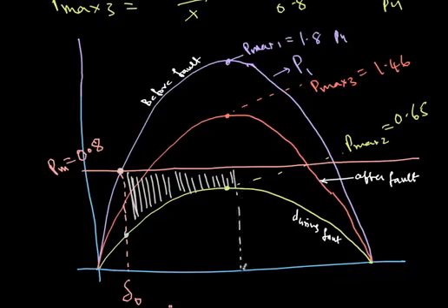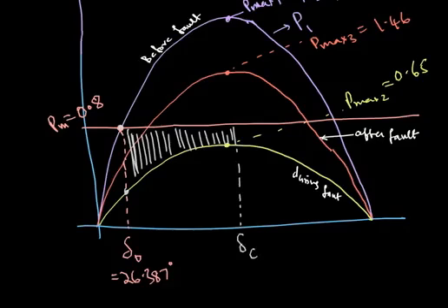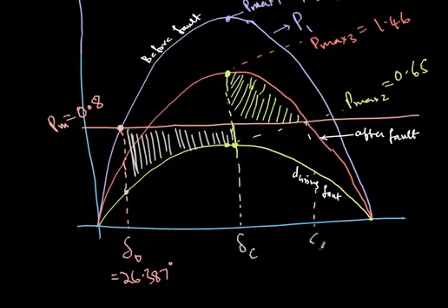the fault is cleared. So let's denote this as delta C. Here I am assuming that the critical clearing angle is delta C. That's what I want to find out. This is unknown. Then I'll directly jump to this point from this point, because now I am on this curve, because the fault is cleared. This red curve will be what is there. So mechanical power is still 0.8, electrical power is almost here. So this area will be my decelerating area. And when these two areas are matching, maximum it will swing up to here. That is delta max. And then it will come back.